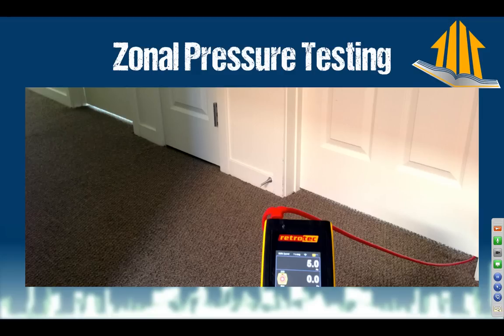So here, if the blower door is not running, we just had the air conditioner running, you can see that on the right, the undercut on that door is very slight. I can see hardly any sunlight. On the left, I can see a lot of sunlight on that door up at the top left. This door that's closed has very little space for air to get out of it, and there's only a supply register in there.